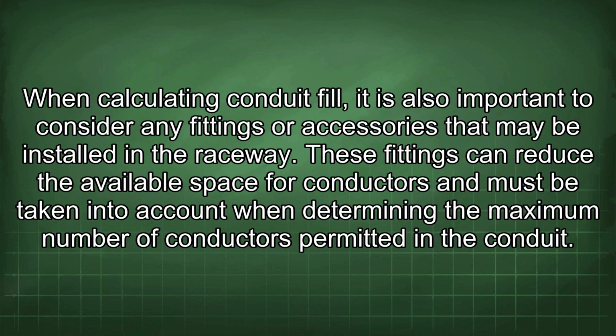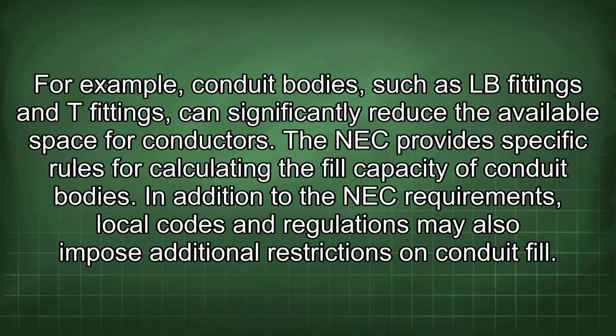When calculating conduit fill, it is also important to consider any fittings or accessories that may be installed in the raceway. These fittings can reduce the available space for conductors and must be taken into account when determining the maximum number of conductors permitted in the conduit. For example, conduit bodies, such as LB fittings and T fittings, can significantly reduce the available space for conductors. The NEC provides specific rules for calculating the fill capacity of conduit bodies.